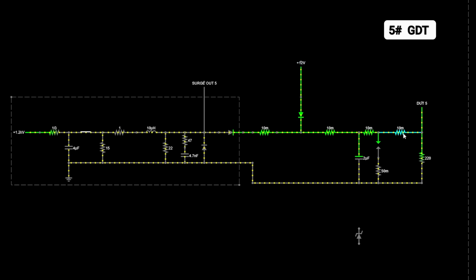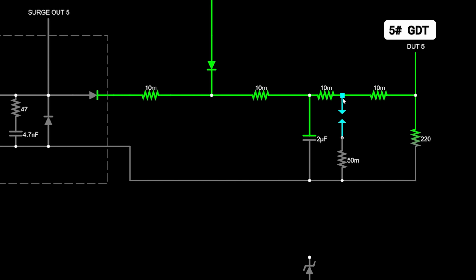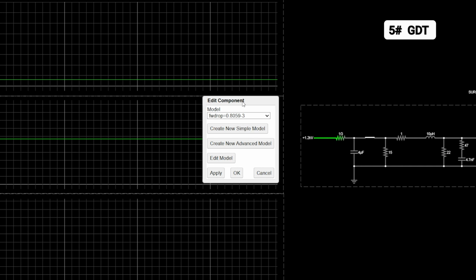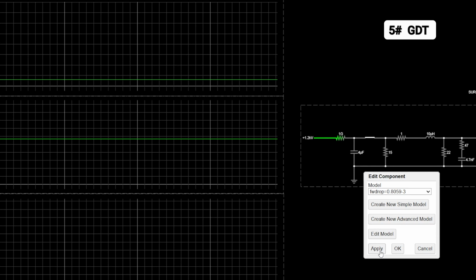It will function just like it did at the start because that voltage and current was removed from it. So how do we stop that from being an issue? The easiest way is the series element I was talking about. The easiest one to use is a TVS diode again. So if we throw a TVS diode in series with this chain, the Zener diode or the TVS diode I have has a 50 volt breakdown voltage.